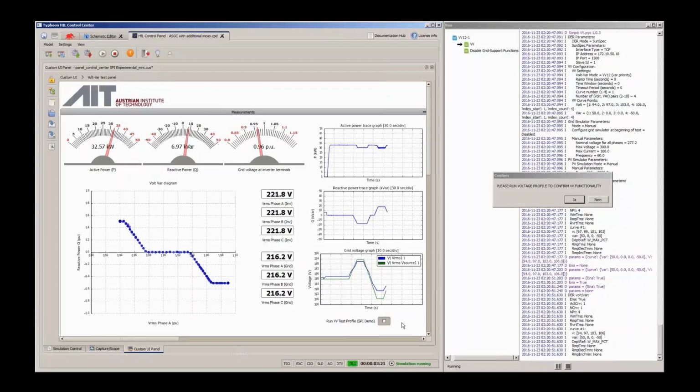The main purpose of these ramps is to determine whether the control responds to decreasing and increasing voltages in the same way, or whether the control exhibits any kind of hysteresis, delays, or other things you wouldn't like to see. That's the reason why we have these hold times and these defined ramps.